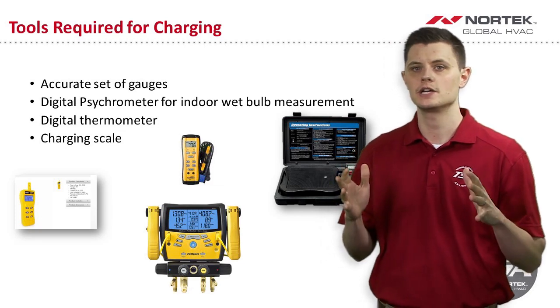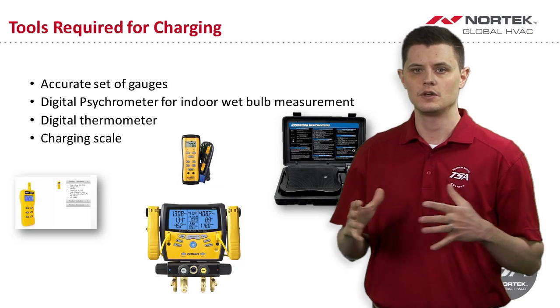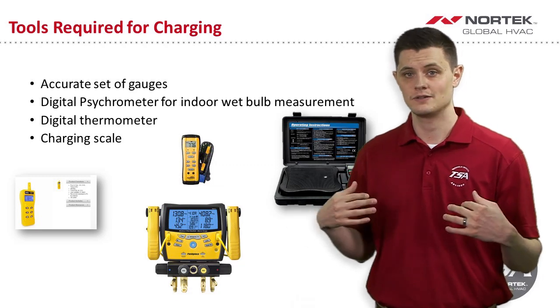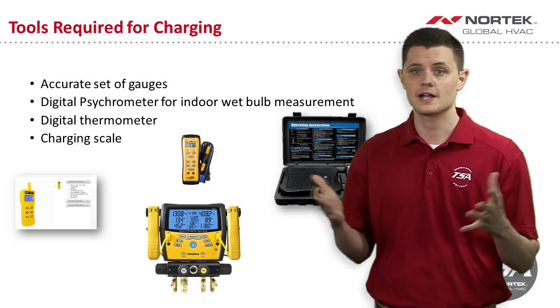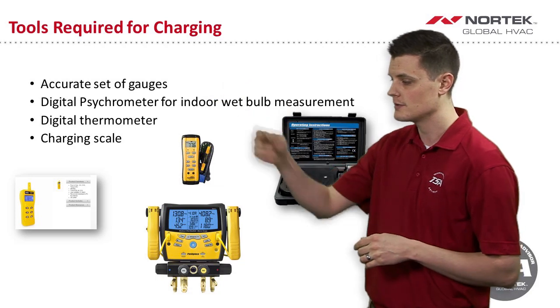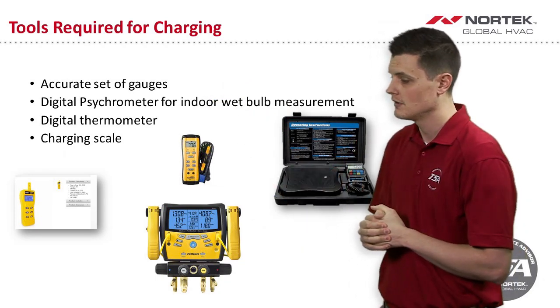I highly suggest that the guys in the field have psychrometers to get the indoor wet bulb, because if they don't know the indoor wet bulb, then the guys at tech service are guessing, which is not going to be as accurate as it should be. So the biggest thing is we need a digital psychrometer for the most accurate measurement.